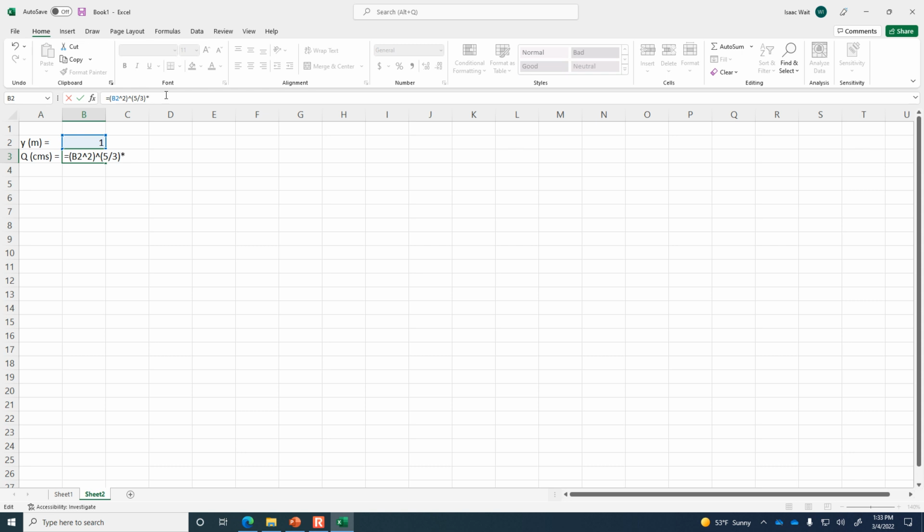Times the slope to the 1/2, so that was 0.01 to the power of 0.5, divided by 0.013 times 2.83 times y, and then that's to the power of 2/3. Well, I need to be careful though, because the 2/3 does not include the n value. It's just 2.83 times the depth. There we go. So if you're doing it on your calculator, hopefully we'll get the same thing.